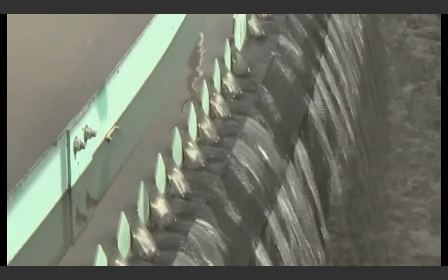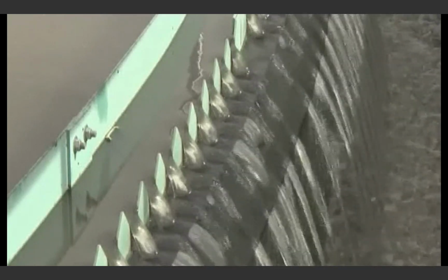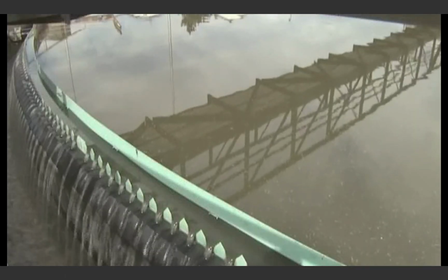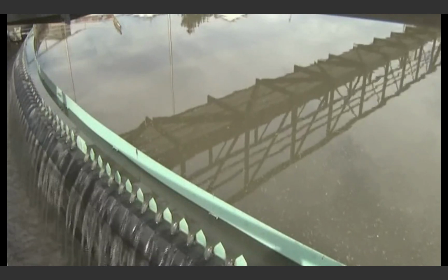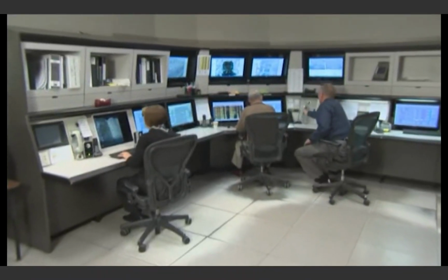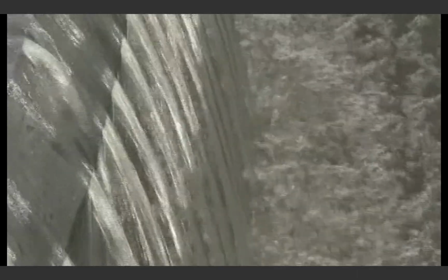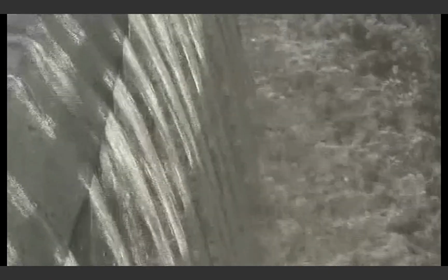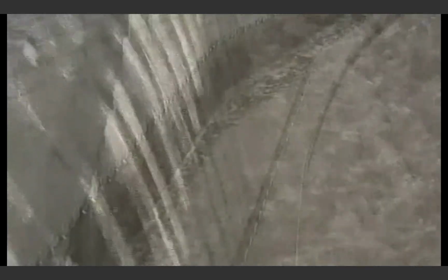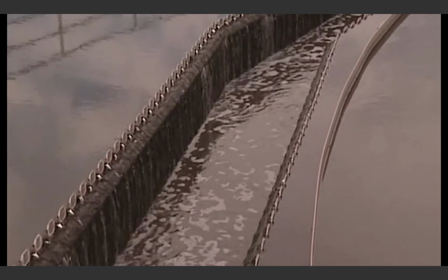A weir is like a small dam, gate, notch, or other barrier placed across a basin to help regulate water out of a basin. The weir overflow rate is used to determine the velocity of wastewater over the weir. The velocity informs the operator about the efficiency of the sedimentation process. At constant wastewater flow, the shorter the length of the weir, the faster the water velocity will be out of the basin. Conversely, the longer the weir length, the slower the velocity will be out of the basin.